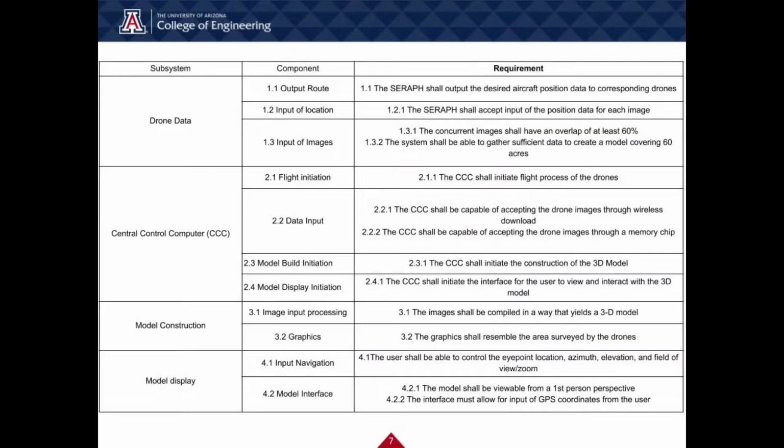The word Seraph is defined by the Oxford Dictionary as an angelic being, which is what our system is designed to emulate. The most notable requirements that drove our design were that the model shall be compiled from images gathered by a swarm of 2 to 4 drones, the central control computer shall initiate the flight of the drones, the central control computer shall initiate the construction of the 3D model, the Seraph drone data shall be downloadable to the central control computer, and the Seraph drone image collection capacity shall be scalable to cover greater than 60 acres.